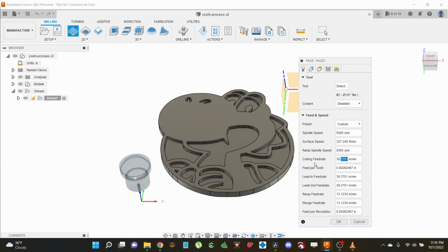Well, Carbide Motion and similar CNC control software lets you adjust the feed rate while it's running, anywhere from 10% to 200%. I just start with 100 inch per minute and know that that will give me a working range between 10 and 200 inch per minute, and I can easily find the sweet spot while it's running.